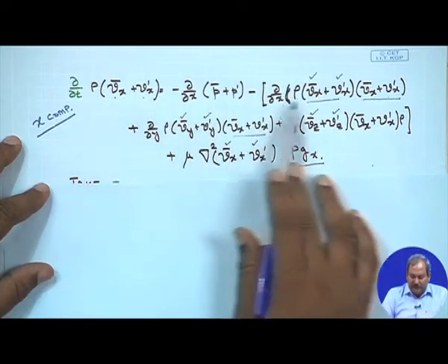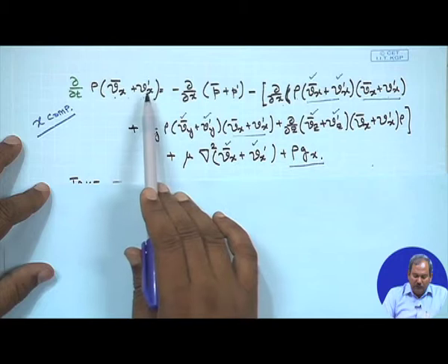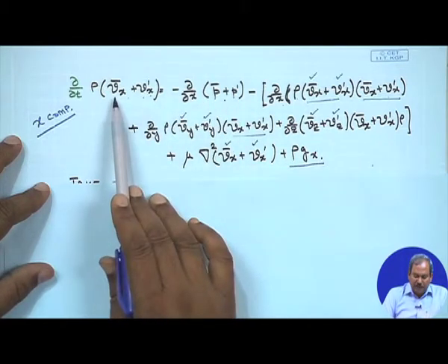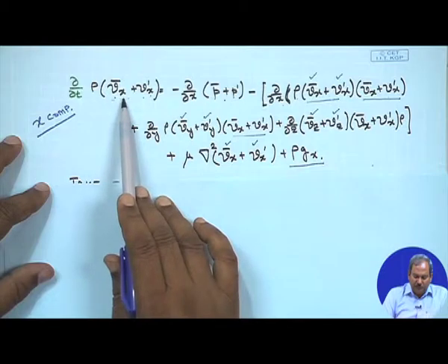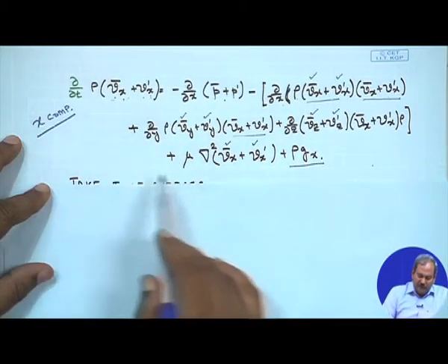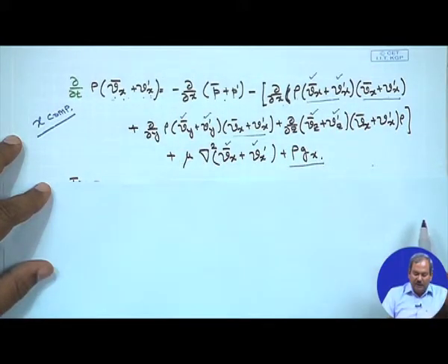So there is nothing different, nothing unusual about this equation, except all velocity terms and the pressure term are expressed as a sum of a time smooth component and a fluctuating component. A similar type of equation can also be written for the equation of continuity.